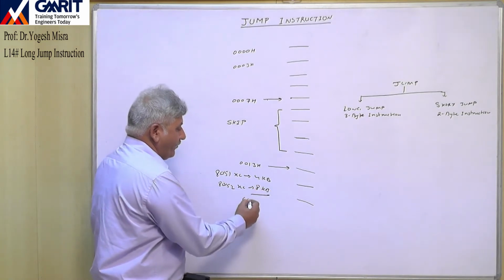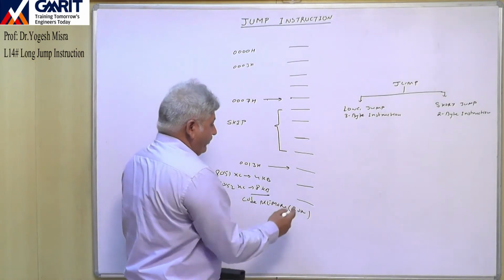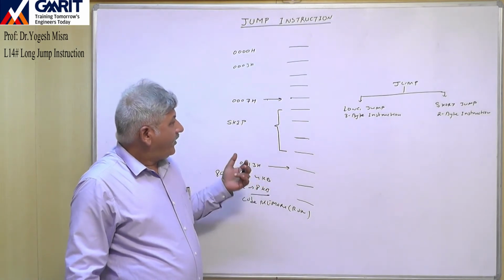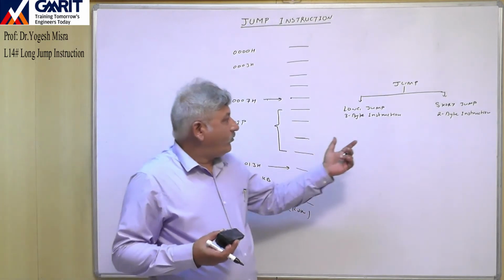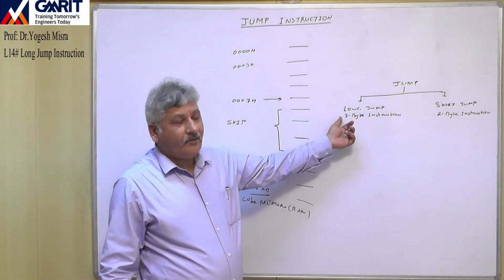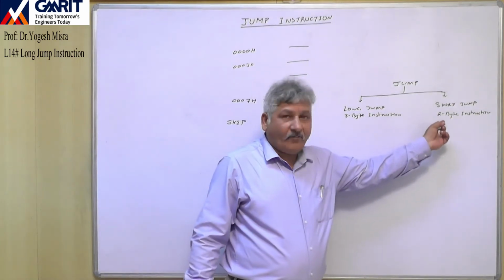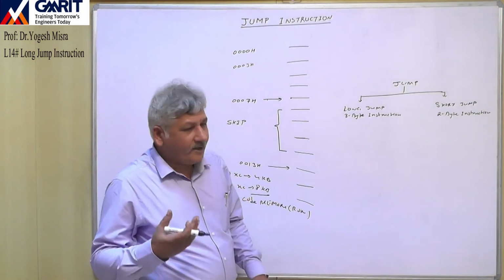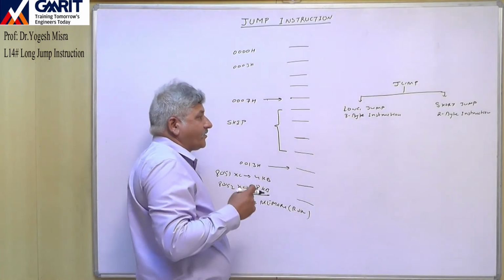These are fixed, inbuilt code memory, so it is better to write a program which consumes fewer bytes. If we go for short jump we can save 1 byte, whereas long jump is a 3-byte instruction. But obviously, if we save 1 byte, we save it at a certain cost, which we will discuss afterward.